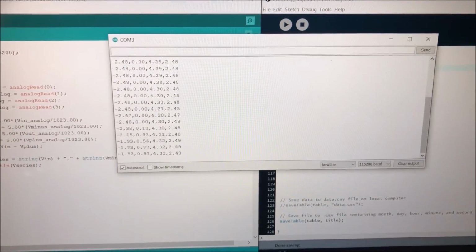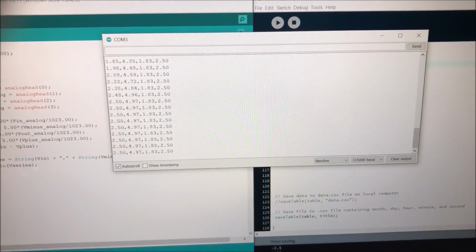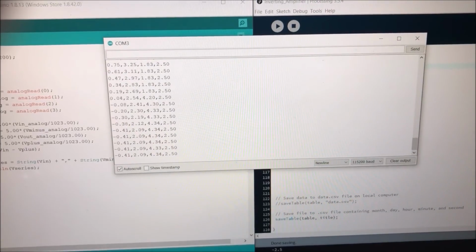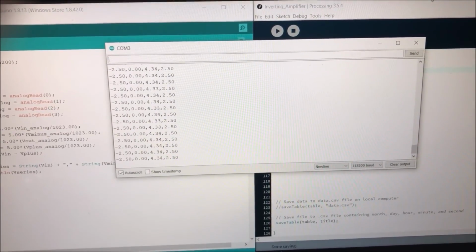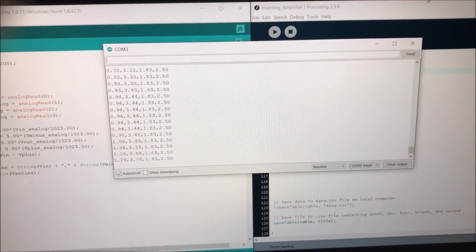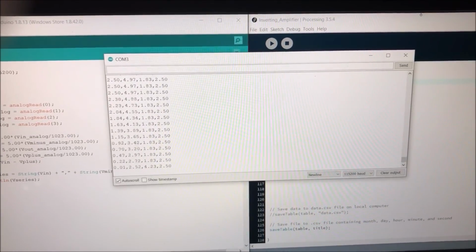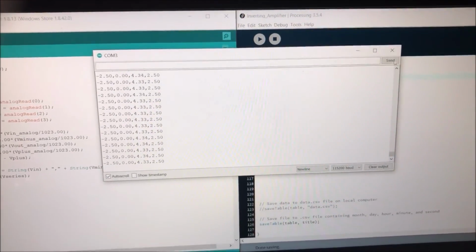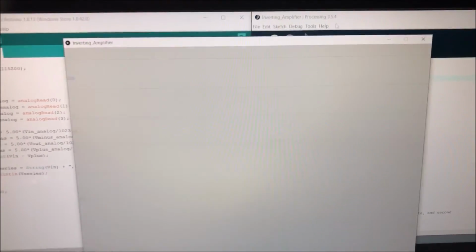We can see that the inverting input voltage varies directly with the input voltage, which is to be expected. As in the previous circuit, this setup acts as a voltage divider. The output voltage, where it once varied, now is explicitly one value or the other, depending on the charged or discharged state of the capacitor.